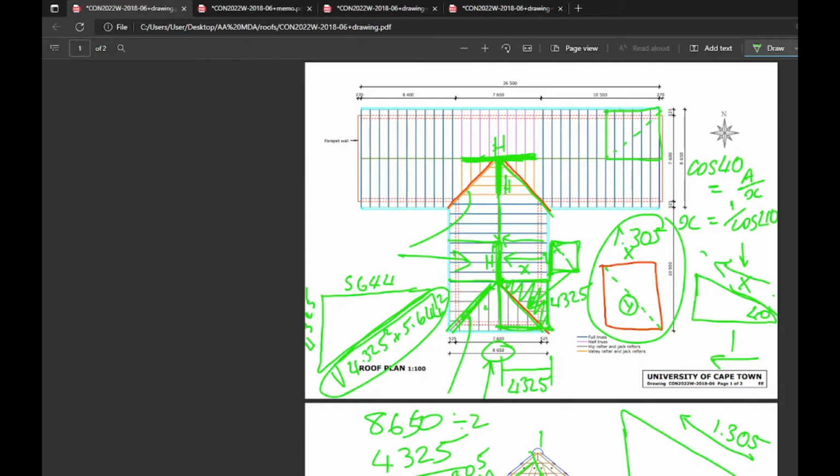It wouldn't be correct. That might be a measure, actually, of a tie beam. If there was a tie beam that ran from the corner to the center, you would just take Pythagoras of the square to get this bisecting line. That would be a tie beam. But in the case of rafters, you'd need to account for the slope. You find your factor to get your slope so that this whole edge is raised now. You've got to visualize it. Flat square, these ends stay flat. Flat and flat. Okay? This end is now raised. And by what factor? Well, you have to use trig to find how much this face elevates. Let's go.